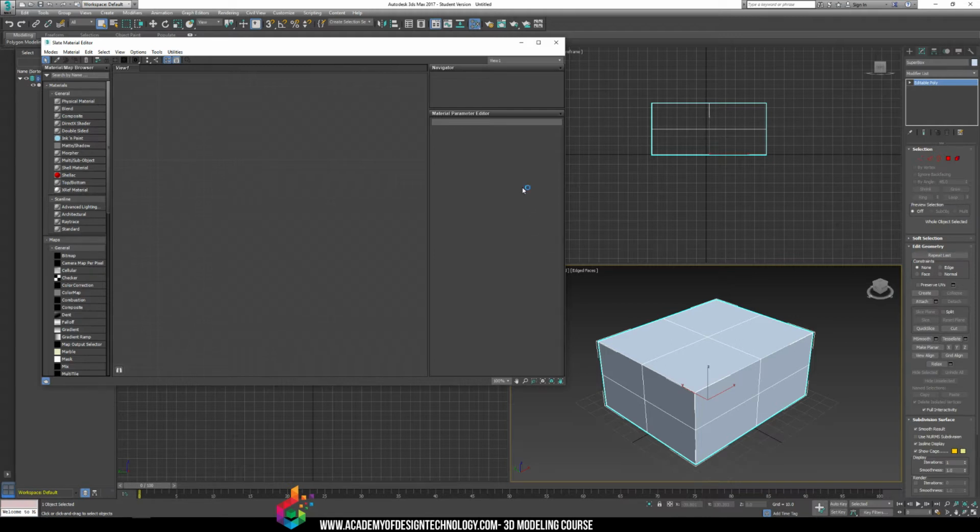So what you want to do inside 3D Studio Max, and for now we're going to play around with what's called standard materials, is we're going to create our first standard material. We go to Scanline and we look and we see a standard material right here. You can left click on it once and it does nothing. Double click on it and it creates a standard material for us. If we double click on the little orb, it'll expand that orb so we can see exactly what it looks like. So if I look at it, it's a standard material and it's gray.